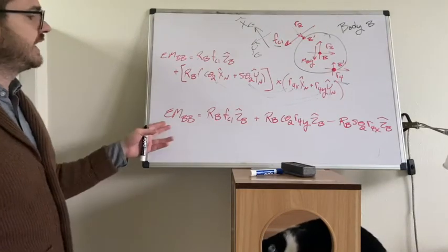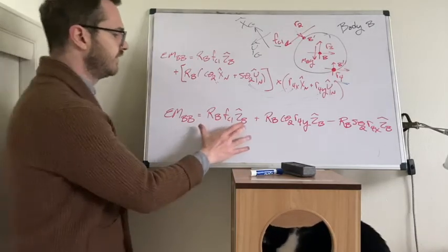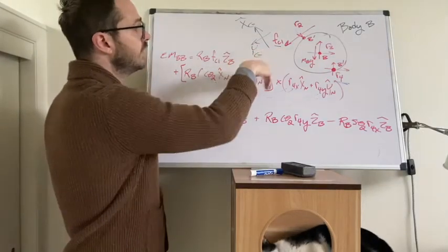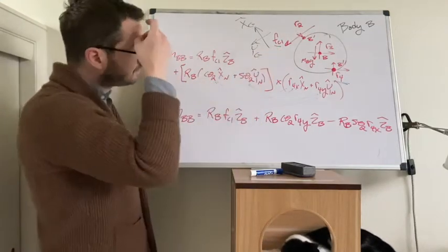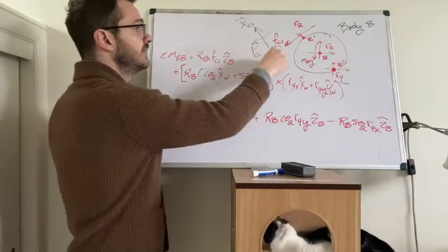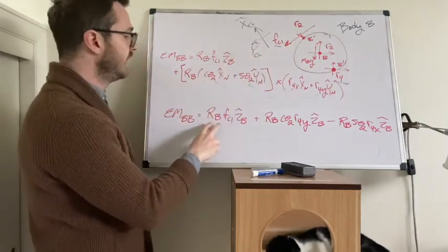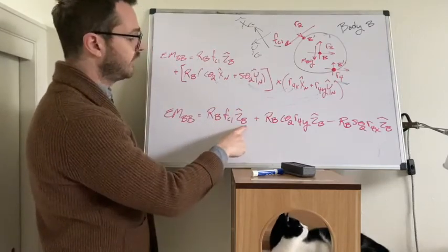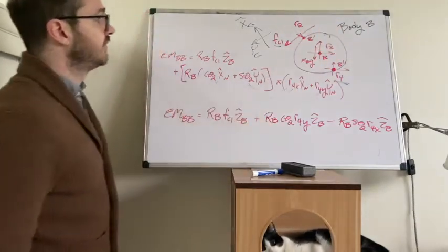As always, check this. Does this make sense? Do we agree with this? This first term, RBFC1, so we're looking at the friction force. Again, when you do your free body diagrams, you pick which direction to put these arrows. And if at some point in the dynamic analysis the friction is actually pointing the other way, well then the value just switches, right? The sign goes negative. So if we assume FC1 is positive as we have drawn it, that's going to create a positive moment, which makes sense. Again, it would make your disc want to spin this way. So that's a positive moment.